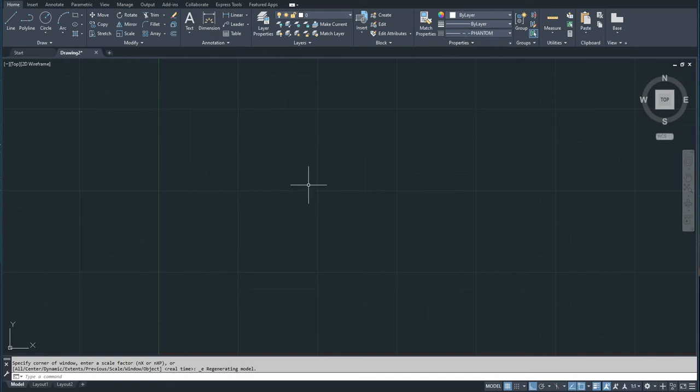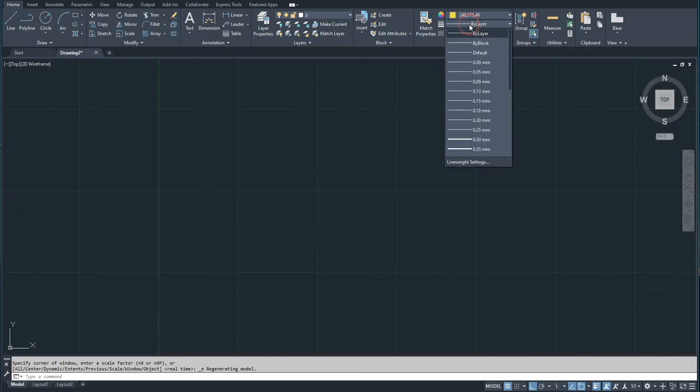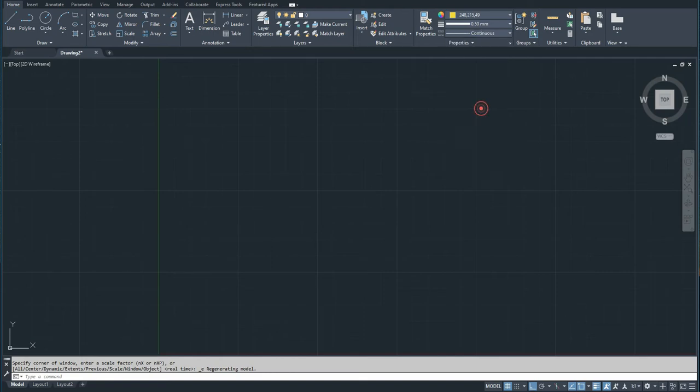Next step, guys. I told you if you want to change the properties, we can change the properties after drawing the part or before. But the professional way, you have to prepare the drawing. As an example, you have to choose the color from the beginning. Say that yellow. You have to choose the layer. Keep it. The line weight. Sorry, I will select 0.5. The line type. I will use the continuous. Let me select continuous. This is continuous.